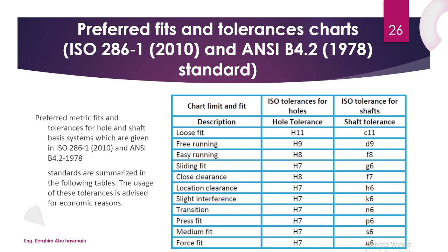Here I put tables, preferred fits and tolerances charts. The preferred metric fits and tolerances for the hole and shaft based systems, which are given in ISO 286-1, 2010, and ANSI B4.2, 1978, are summarized in the following tables. The usage of these tolerances is advised for economic reasons.